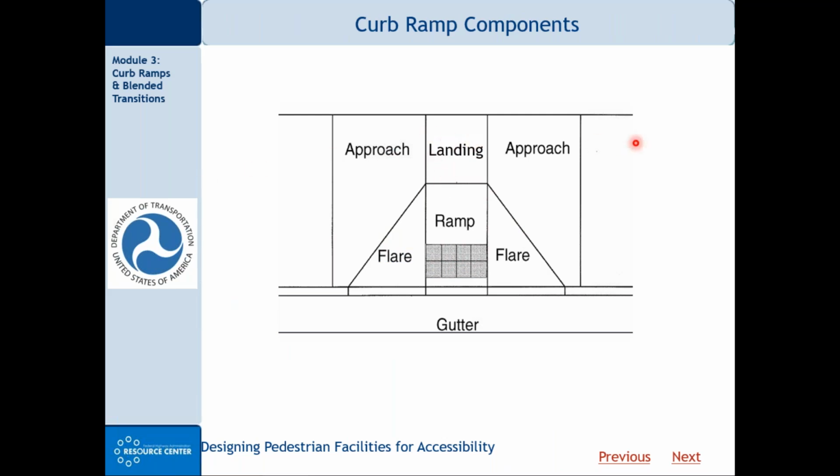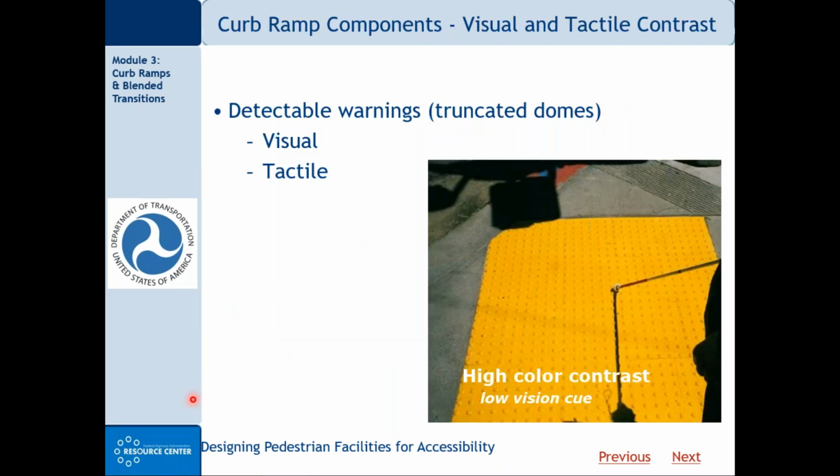So it looks like the PAR portion of this pedestrian circulation path would be towards the back of the sidewalk here. And then because this ramp is in the pedestrian circulation path, again, pedestrian circulation path, back of curb to back of sidewalk, PAR is this portion back here. But since this ramp is in the pedestrian circulation path, it needs to have flared sides, and we'll talk more about those. I mentioned that the ramps need to have detectable warning surfaces at the base of the ramp.